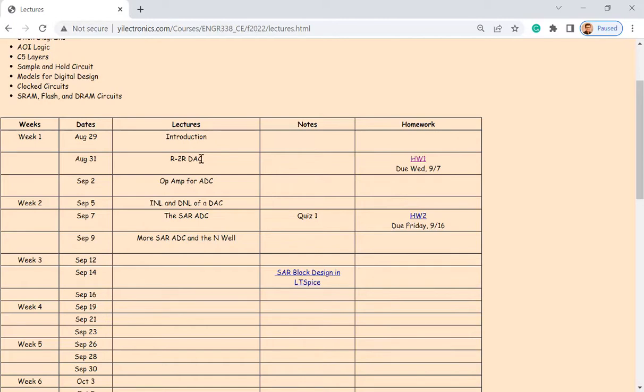Maybe 20 different layers of materials can be used in the silicon fabrication process. And one material is called N-well. It's an N-type material, and you can use that material as a resistor. So you just draw all these rods on the chip, not real rods, to form all the different resistances.